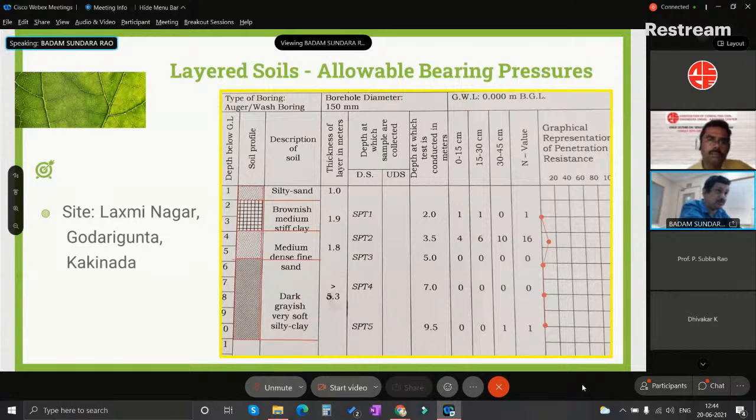Suppose there's a private work and we are compromising, with some design techniques we are capable of adapting or designing, then we can have a reduction of the settlements that we will discuss just now, and that can be allowed even while slightly crossing its permissible value of 75 mm.